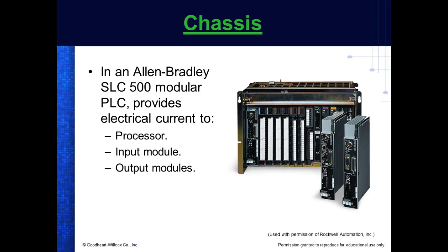So even for most PLCs, we can buy different. It comes with communication built into it, of course, because we have to have some means to hook our computer up to it, right, and program it. But then most of them give you the ability to go to other modules. Some of the other communication standards that are out there, like Profibus and DeviceNet, and Ethernet IP, and Fieldbus, and there's a lot of them out there.